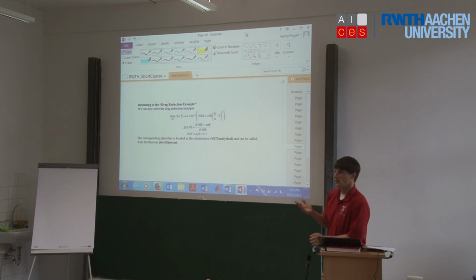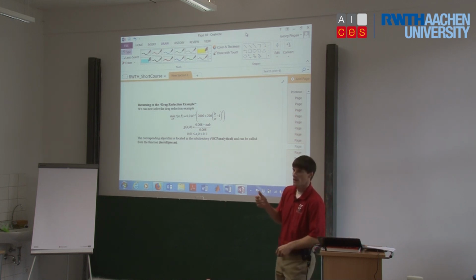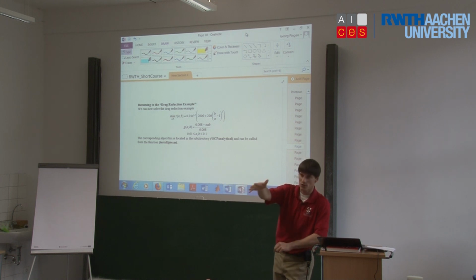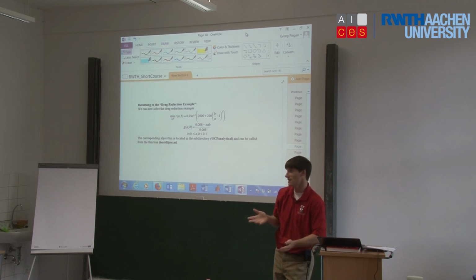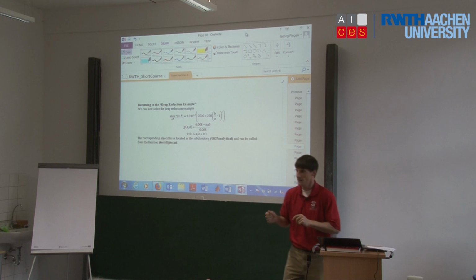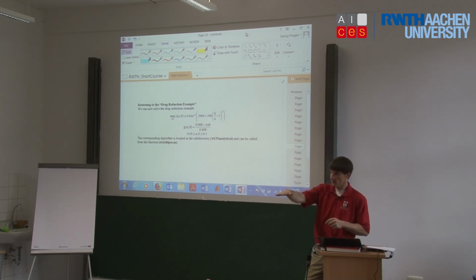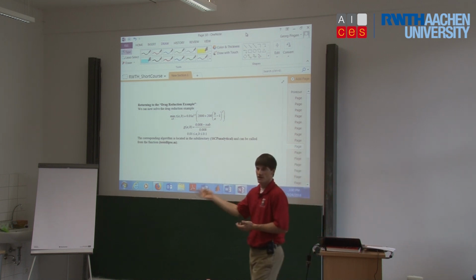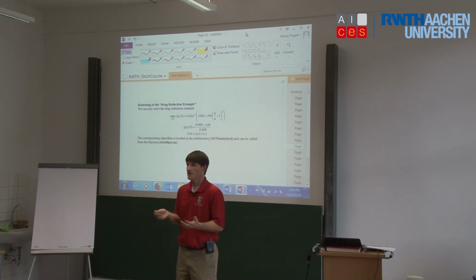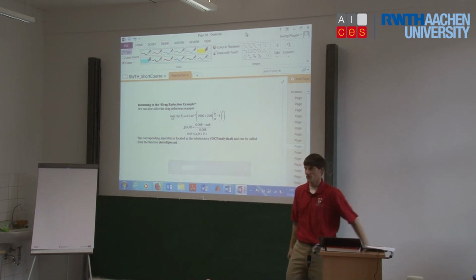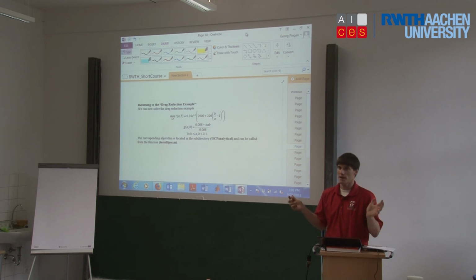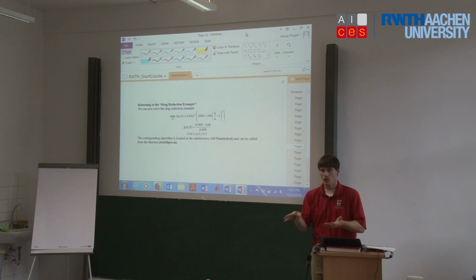In order to allow us to solve some of the optimization problems within a few minutes instead of a few hours, I had to decrease the mesh density. That meant the program didn't converge to as high an accuracy, and so it didn't stop, and it kept going into a solution that made no sense. Afterwards I came back to my computer, looked at it, and realized it had actually got to an optimum, but then just kept going, because I told it I need an optimum that's this good, 10 to the negative 6, and it didn't find it. So it got to the best point, and it said, well, I have to go somewhere to try to make it even better, and it went somewhere off. At that point it just kept getting worse and worse. I'm not exactly sure mathematically what the reason is for that divergence in the SCP, but that's something you want to watch out for just a little bit.